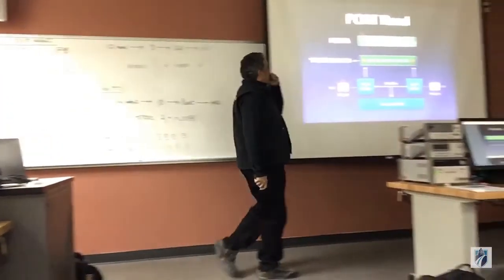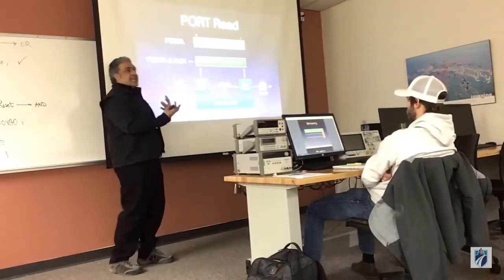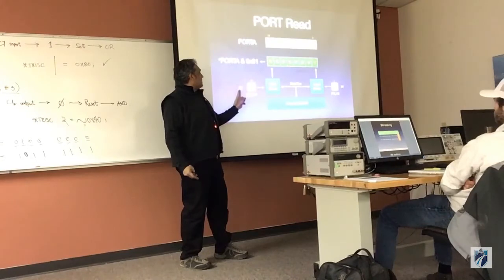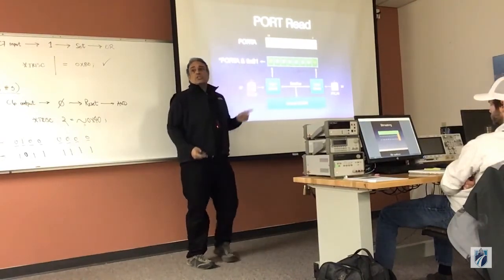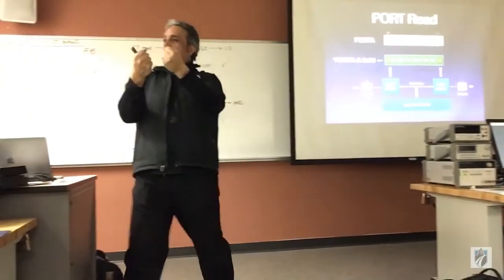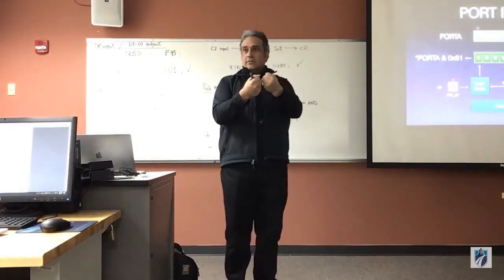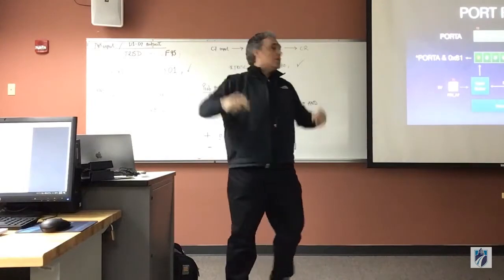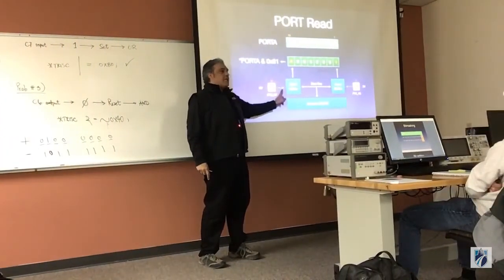So, here we go. If you're going to do a port read, then it begins the other way around. You actually begin by manipulating the voltage. Look at the arrows, right? The arrows are moving backwards now. So notice that the action is now physical. This is not a software action. The software action is the trailing end of the entire sequence. So I actually take pin 13. Notice the arrow is looking in. That means that this was set up as an input.